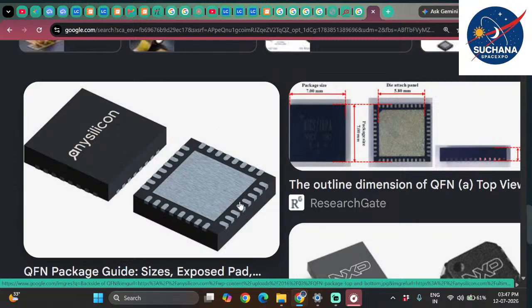So basically in the schematic section, if you are trying to place this particular symbol in the schematic window, there you will be placing the symbol, right? So those symbols labeled with VCC, ground, all these are originating from these pads only. Basically these pads have a reference name like VCC, ground, serial clock, serial data, SD0, and you are connecting these with the help of the wire tool, let's say, if you want to ground the SD0 pin.